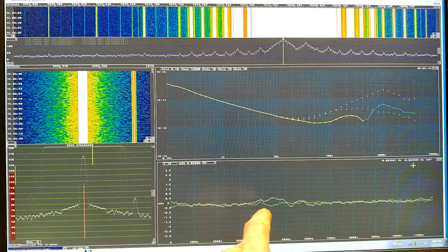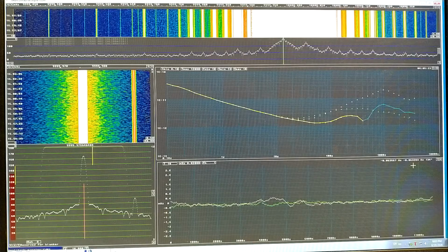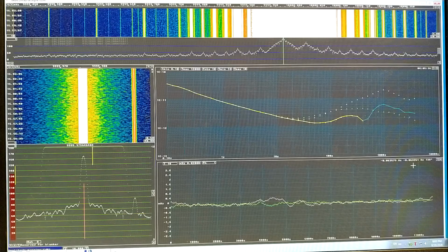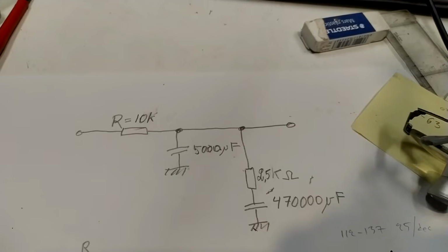There has been an event here that is correlated. It could be temperature, and I cannot say for sure the frequency content of it, but I don't think I will have any problem with correlation between the local oscillators when measuring down to 0.1 hertz from the carrier, at least.